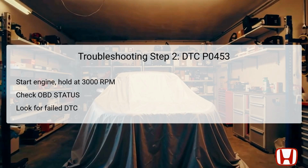Conversely, if the status shows past or intermittent failure, the system may be functioning correctly at the moment. Therefore, further investigation is needed to look for poor electrical connections or loose terminals within the FTP sensor circuitry.